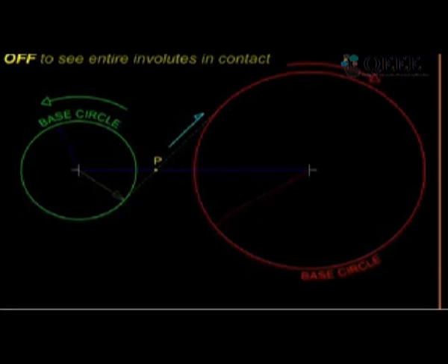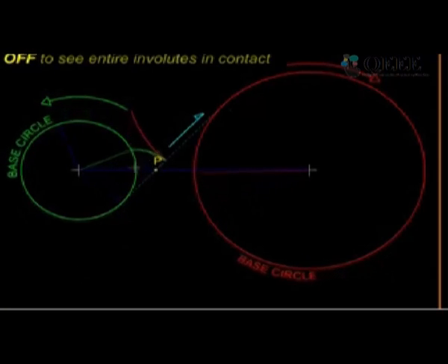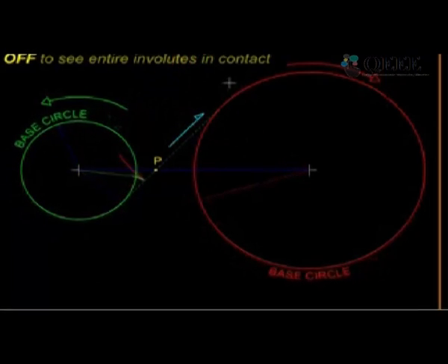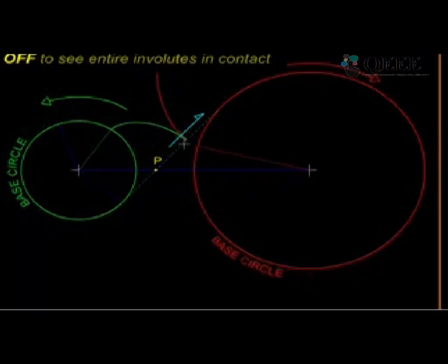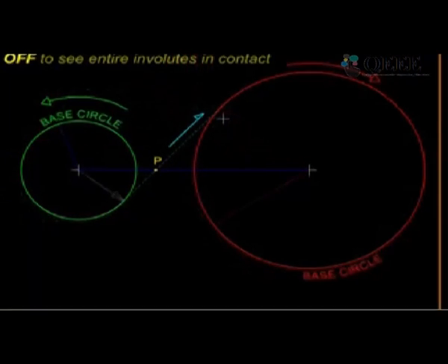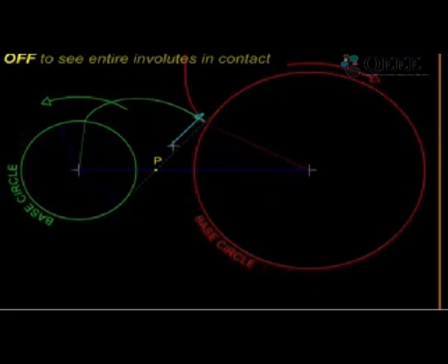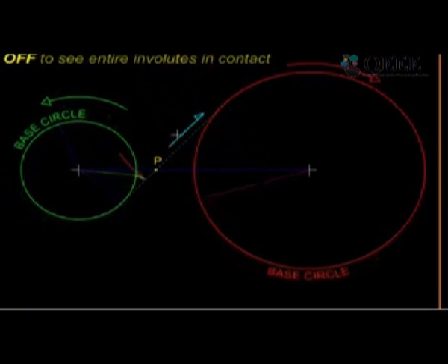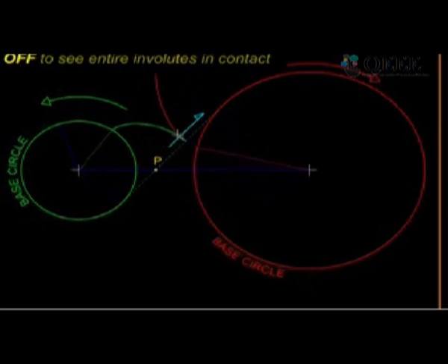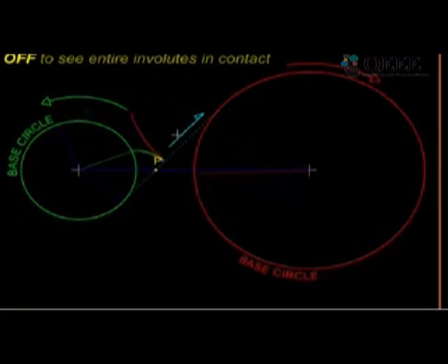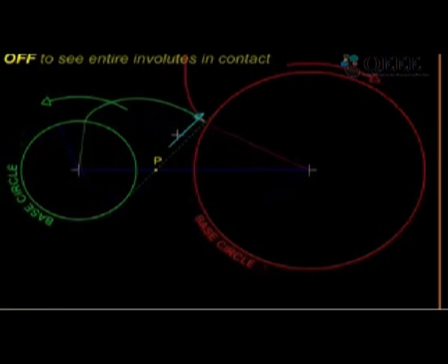So this is how it looks. So there is a green involute on green pulley, and the red one is getting traced on the red one, and they are always making a contact, and a direct push is applied, thereby the motion is transferred. So there is no chance of slip. So we are not only getting a constant velocity ratio, but we are also getting a positive drive.